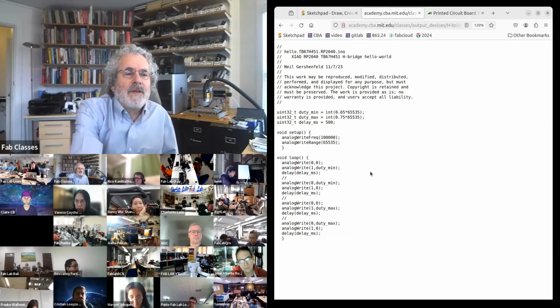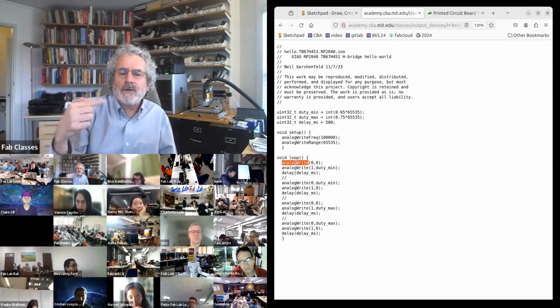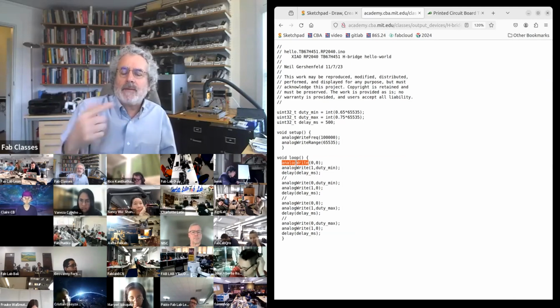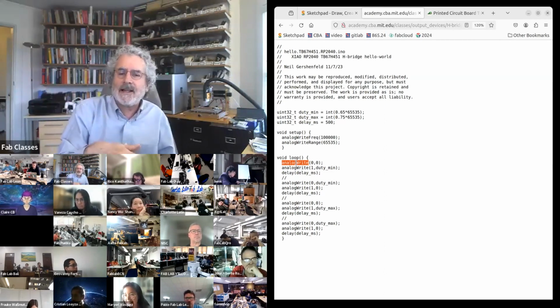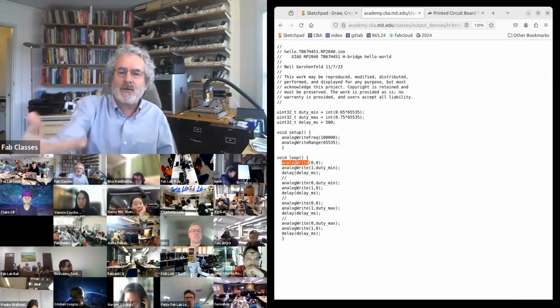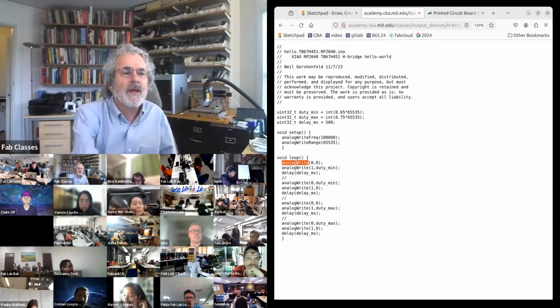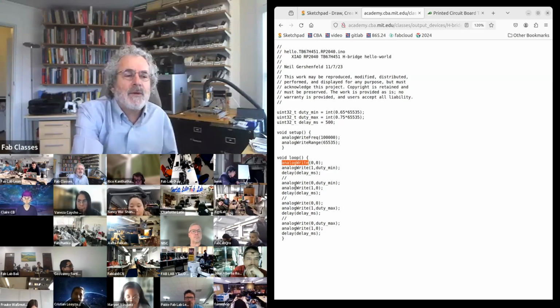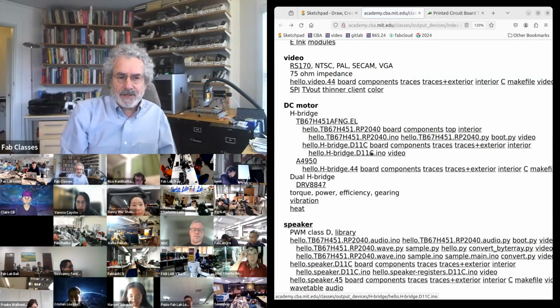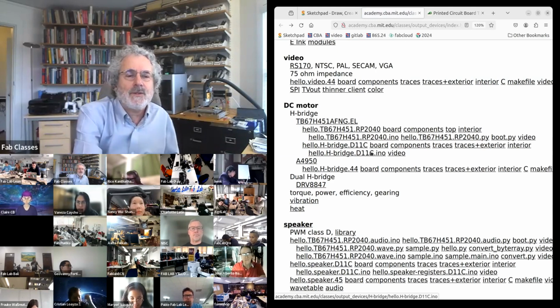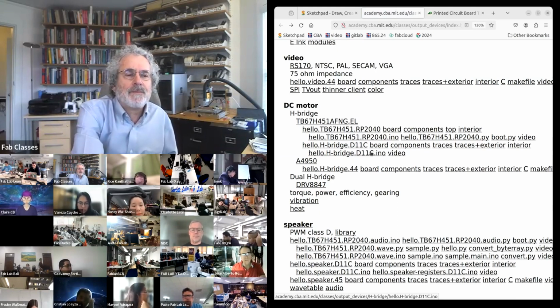In Arduino IDE, here's the similar code. Here, again, I don't like this, but Arduino calls PWM analog write, except for on processors that have a digital analog converter where it's not PWM, it gives you a voltage. It's confusing. But here I'm using analog write to PWM, and then I'm doing the same thing. So that's using an H-bridge to drive a DC motor.